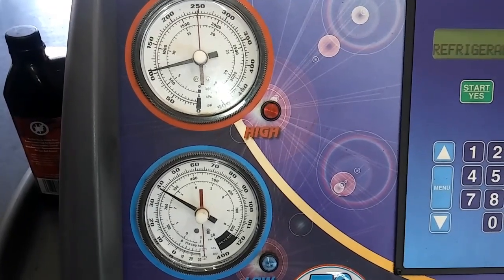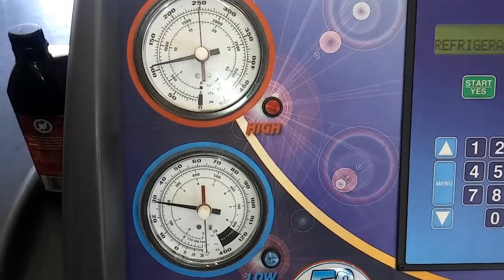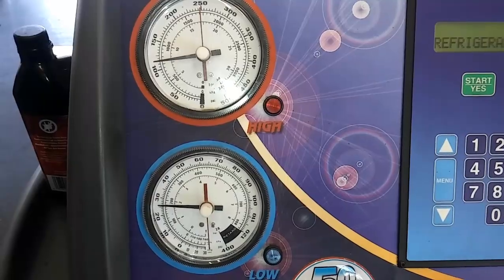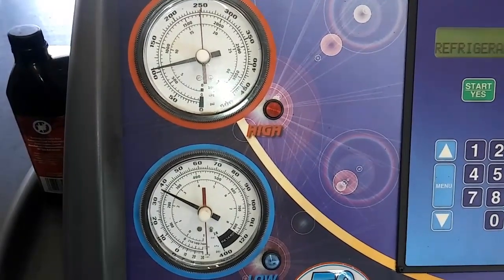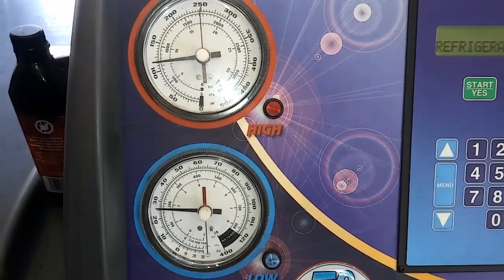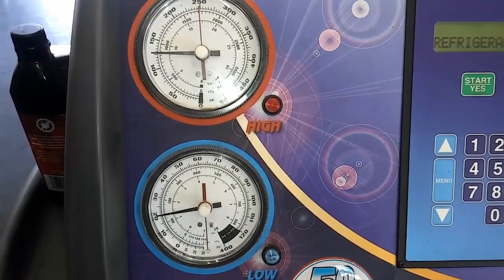Okay, so after replacing the AC compressor, which meant I had to evacuate the system again, pull a vacuum, and check on it, we have our gauges hooked up here, and it's running, and you'll see the low side is pulling between 25 and 40 psi, and the high side is above static pressure, so the system's now working. Okay, so that system had multiple failures. It had a leak, the AC compressor wasn't working, and you could see there at the end that the pressures were operating in the ranges they should be.